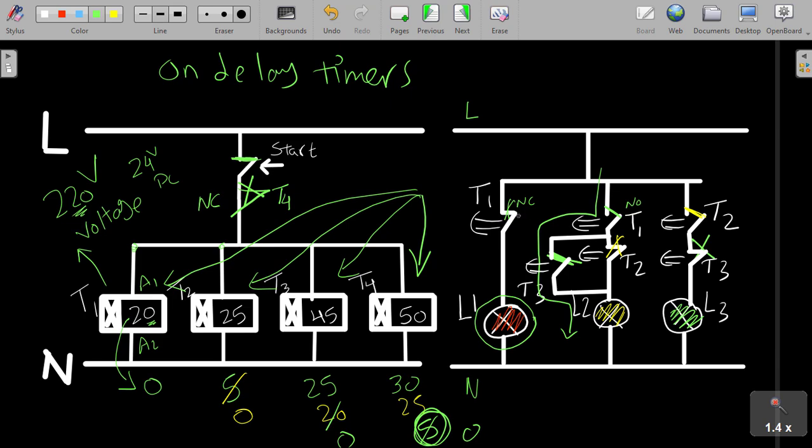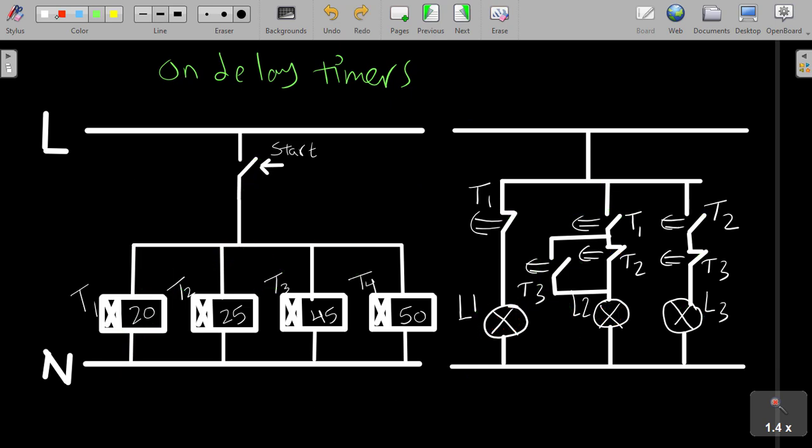So now, when we get back to our normal state, the red one will be turning on again because we have returned to our state. Now our red lamp is turned on again, and they will start to count down again to start the loop from the beginning. We will wait 20 seconds as red, and then we will send a signal to close this yellow one. L2 will start to work because T1 is on. After another 5 seconds, T2 will start working, which will give a signal to L3. And after another 20 seconds, we will return back to L2.